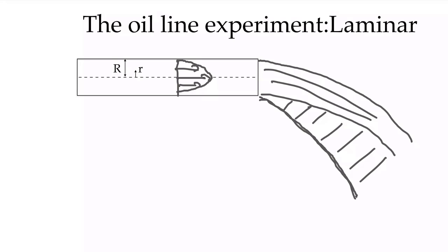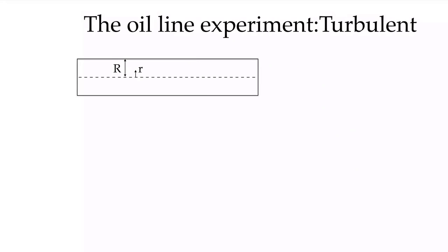When we transition to turbulence, however, we see a very different thing. We no longer see the two pieces. We see a flow that comes down. It's not as translucent anymore. It's a little bit more cloudy because of all the mixing that we have in the pipe. And we also see that it falls a little bit faster than the laminar flow.